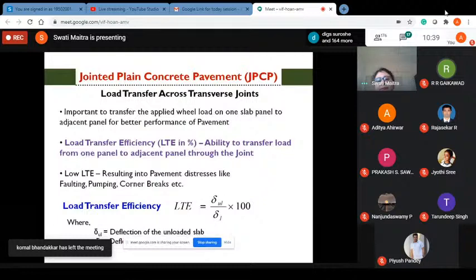Now, several investigations have been done on concrete pavement, and analysis has been done with the latest technology, with finite element modeling. Here you can see a two panel concrete pavement. One side is the shoulder, and it has a base layer and a sub base layer, and below it is the foundation. In between there is also a polythene sheet, to make it an unbonded interface.